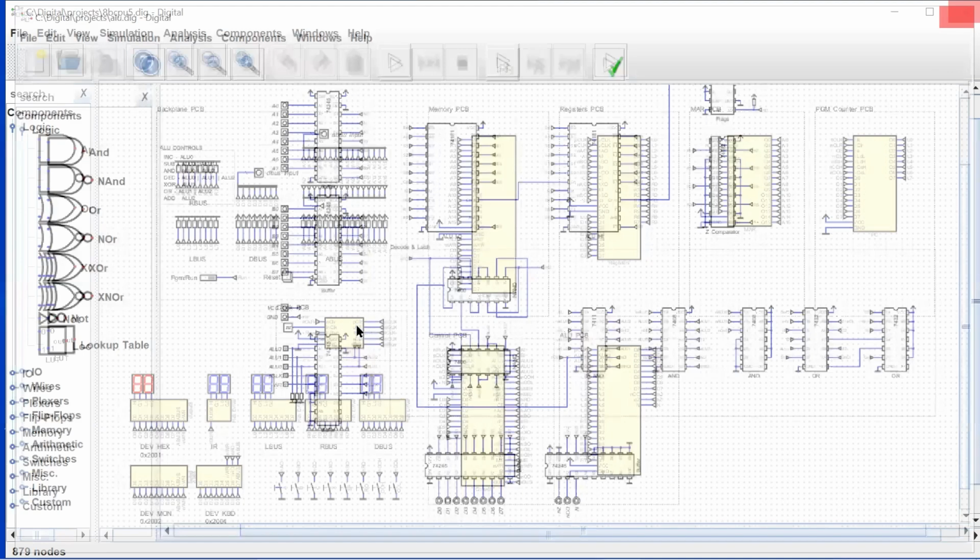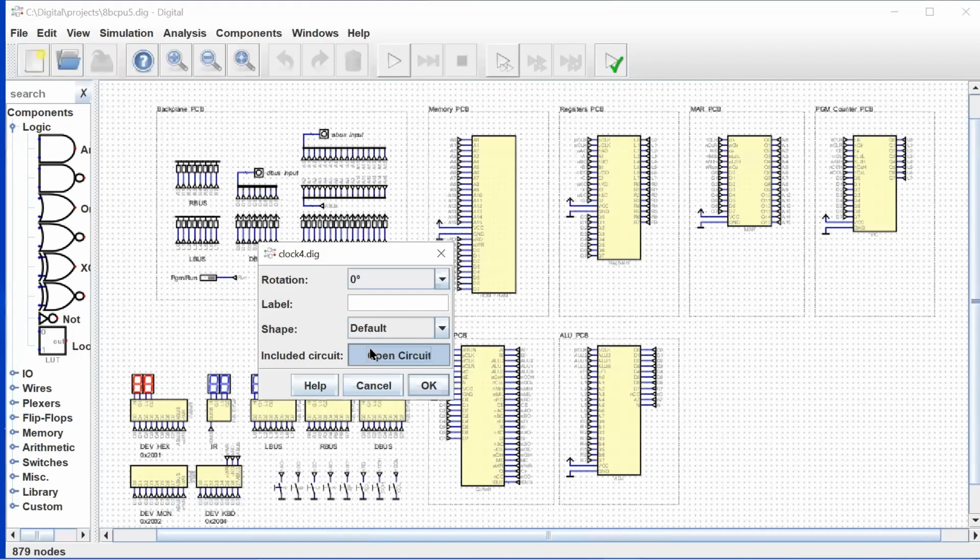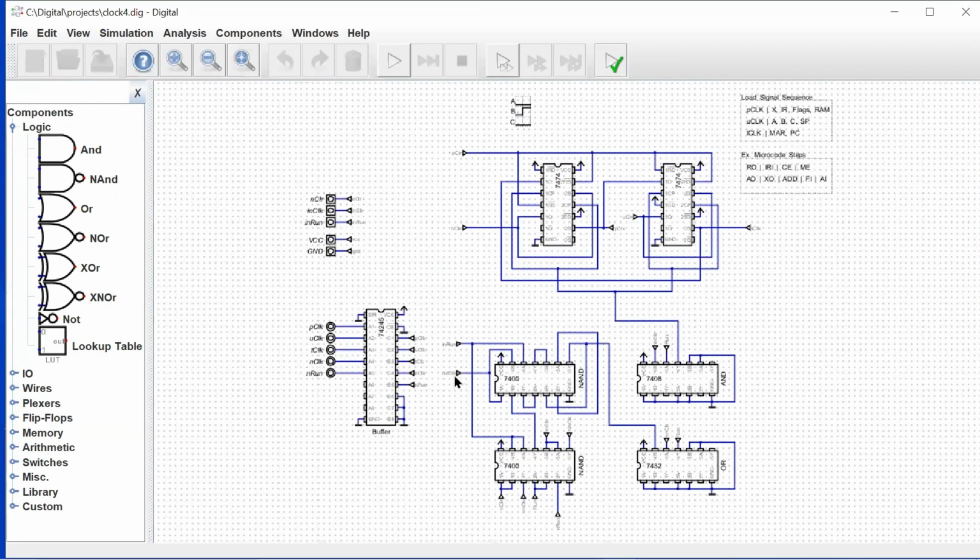All right, and then our clock circuit. So we have the 245s here. I may add one more 245 for these couple of control signals up here, which I probably will do. And that's it. So this 245 is driving the clock signal, right? The clock signal outputs to the backplane.